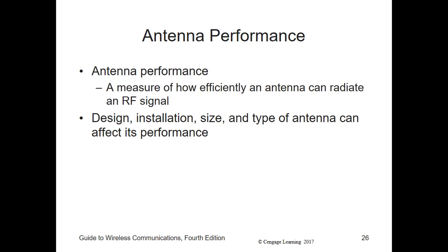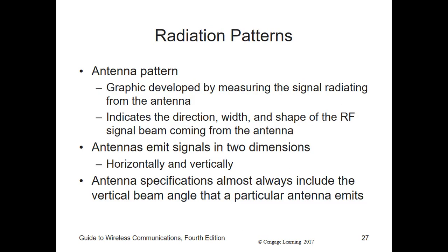RF waves. Now, during the testing phase of an antenna, engineers will develop a graphic called an antenna pattern by measuring the signal radiating from the antenna. The antenna pattern indicates the direction, width, and shape of the RF signal that's coming from the antenna. An antenna pattern is usually drawn as if you're looking at it from the top. So in this case,